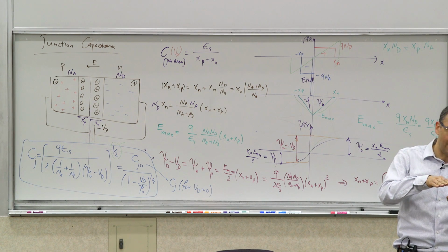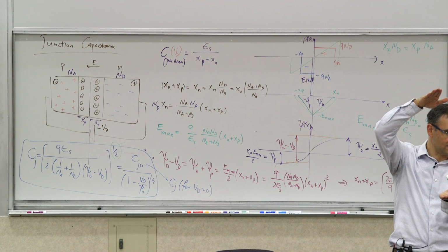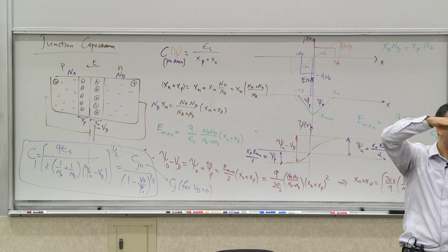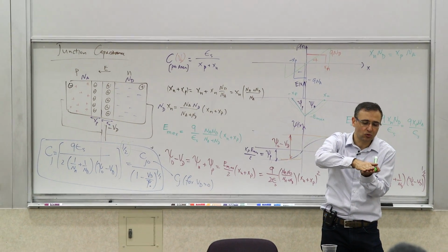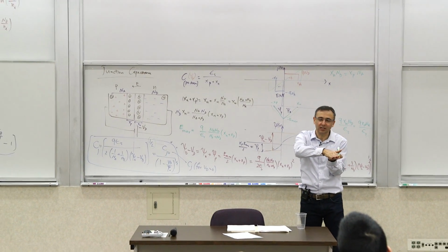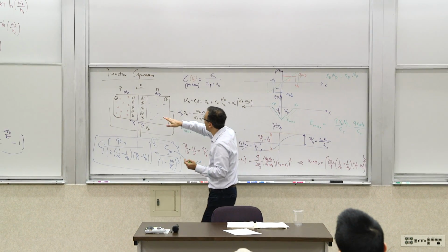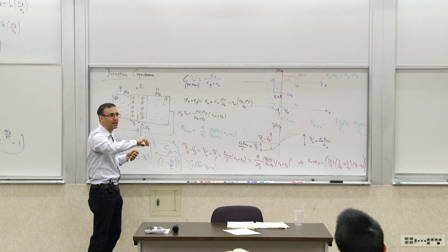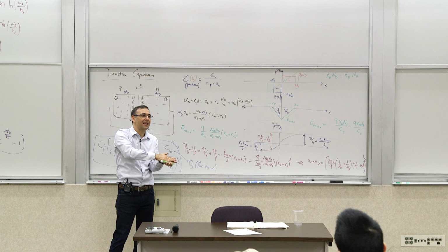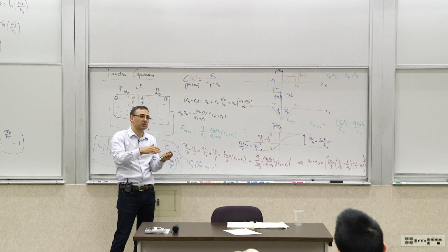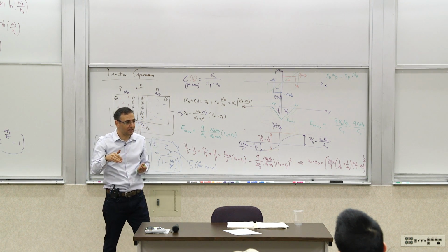One is, when you introduce these dopants, how do you do that? In the old days, what they did, they grew a glass that had a high content of the dopant you wanted to do. For example, if you had boron or arsenic or something like that, you infuse it. And then you heat it up to very high temperatures, like 1100 C or something like that, below the melting temperature of silicon, but close.